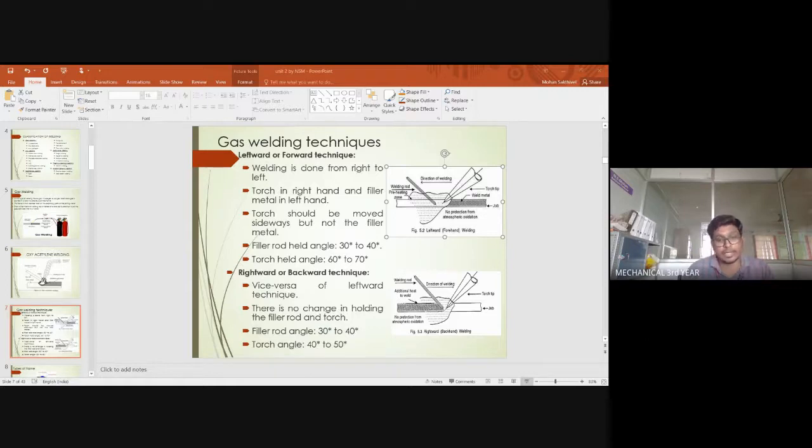It is restricted to flat surface. And here the advancement has also come in the present day. They have also created a rotating table in order to do continuous welding on the surface of a cylinder or something. So this point can be eliminated. It is not restricted to flat surfaces. The advancement has been made now. Carbon steel and alloy steel can be welded, and it is predominantly used for welding carbon steel and alloy steel. And the plate thickness ranges from 12 mm to 50 mm.